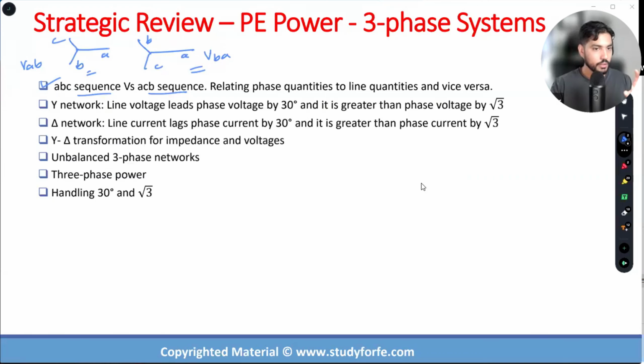So within the on-demand content, I have several detailed lecture slides. I'm going to briefly hit upon a couple of them over here as well. Please make sure that you have a solid understanding of positive and negative sequence. And from a practical standpoint, as I mentioned earlier, I believe in Texas, we use ACB sequence. And in the Northeast, we use ABC sequence. And you can check out the grids and utilities and figure out where else positive is used and where else negative is used. So without any external adjustment between the phase sequence, you cannot just directly hook up and connect the grids. Okay.